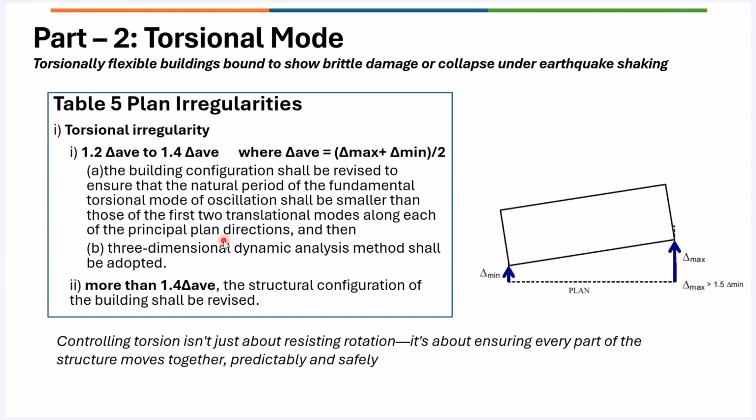So the program gives you the model analysis results to investigate this behavior in detail. But we also have a few other tools we will discuss shortly. The other strategies, let's say this torsional mode checking and all, would be suitable for small buildings or medium-rise buildings. What about high-rise buildings, where you cannot control everything with walls and stiffnesses through the bracings?